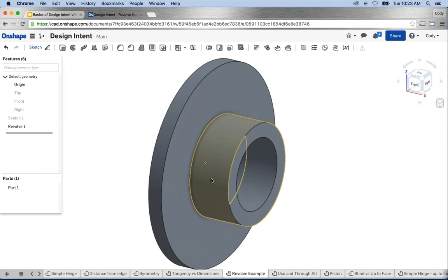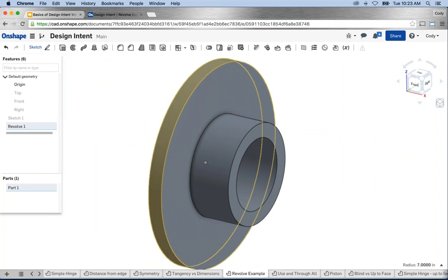Now, what I'd like to do is, I'm building this simple flange. I'd like to build maybe a dozen different sizes of this flange. And this diameter, the inner diameter, this outside diameter, all vary depending on the size that I'm working with. They all grow by a certain amount, so in different nominal dimensions, let's say. So building these different sizes, how I construct that initial sketch directly relates to how much work it takes to build each size. So let me show you what I mean.